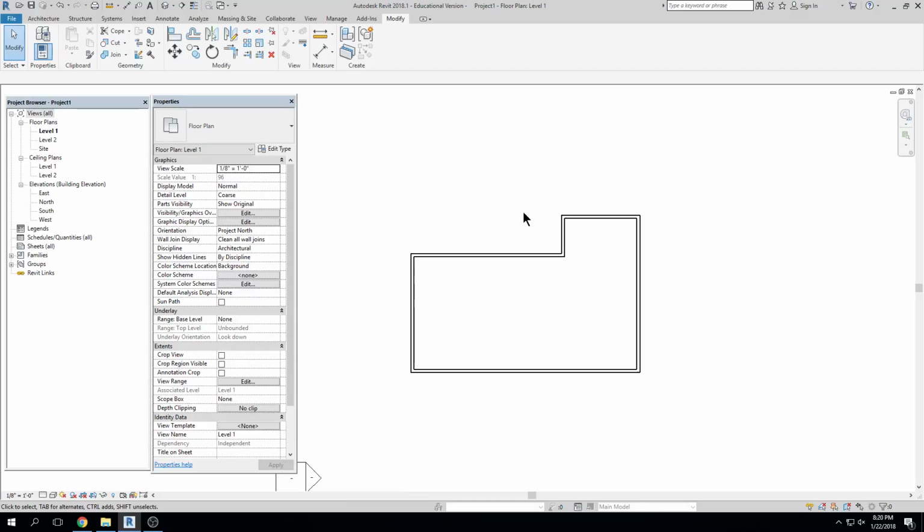So I'm going to start with move. Move allows you to move an object from a stationary point, either a random distance by clicking, or a dimensional distance. Right. So generally, I think a better route of going about using any of these modification commands in Revit is to do a selection set first.